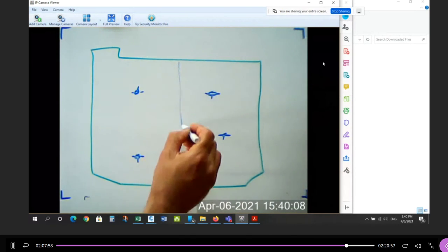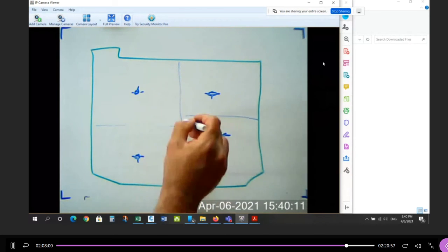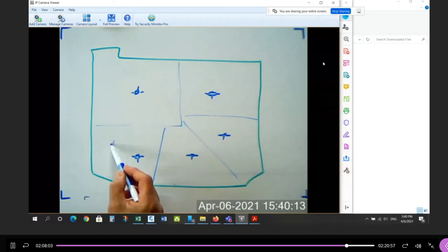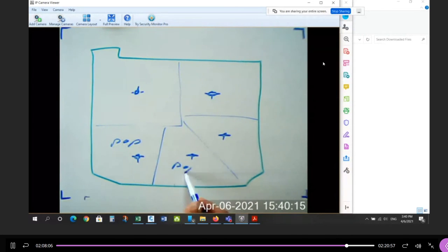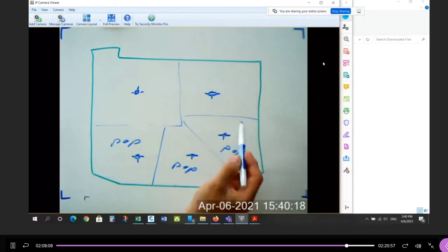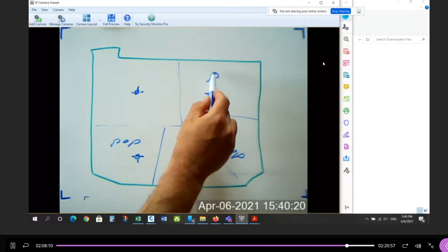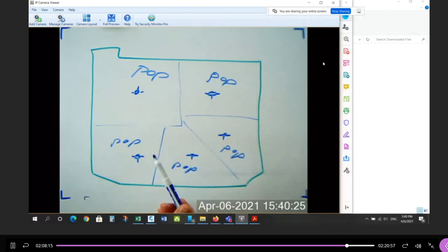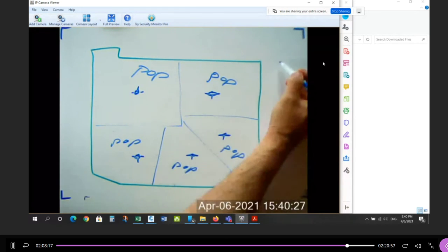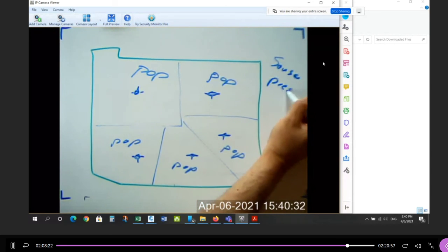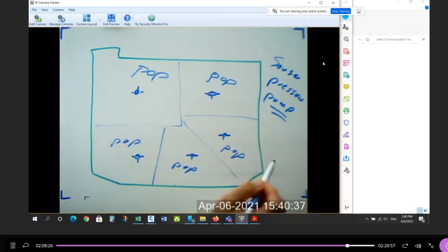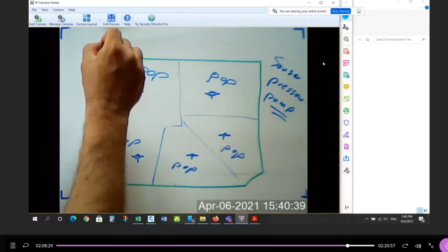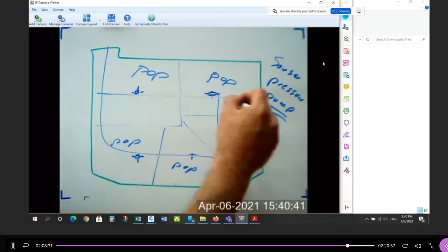So we delineate drainage areas on each hydrant, kind of like this, and you'd have a population in each area. The drainage areas would look similar to the sanitary population, and we calculate a required flow. Then, based on some flow data, we have a source of water and a pressure that we can translate into pump data. All this information is used to charge the system. So our water main looks like this.